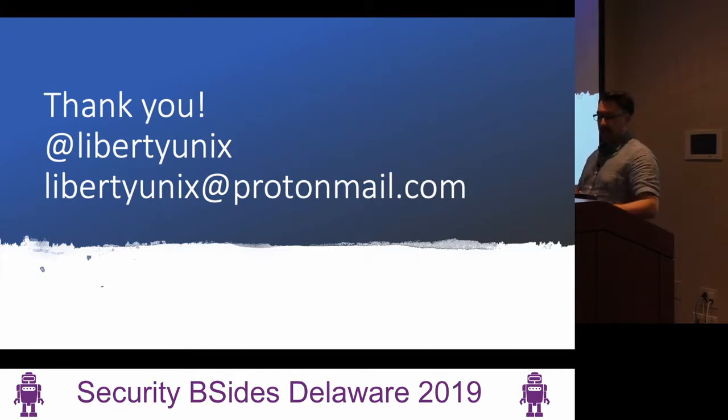Right out of the gate, your standard Bluetooth LE card is said to have 150 meters of proximity. I haven't delved into the antenna, like the Yagi, from the wireless standpoint. I've done wireless engagements where I'm in my car and the Yagi's pointed at the building, but I haven't gone down that rabbit hole for far-distance BLE. But in that talk I mentioned, hacking Bluetooth from a quarter mile away, I'm fairly certain he hooked his Ubertooth or some other BLE hardware device to a cantenna or something to that extent, and was able to extend his distance.